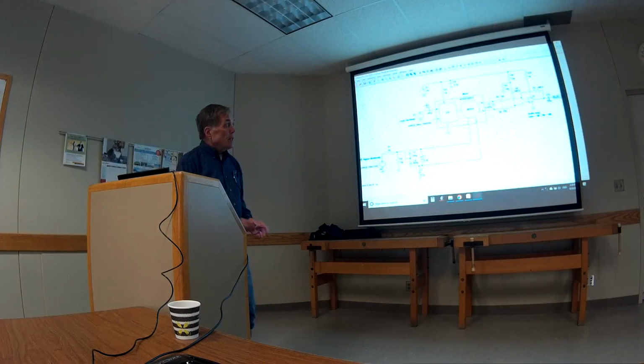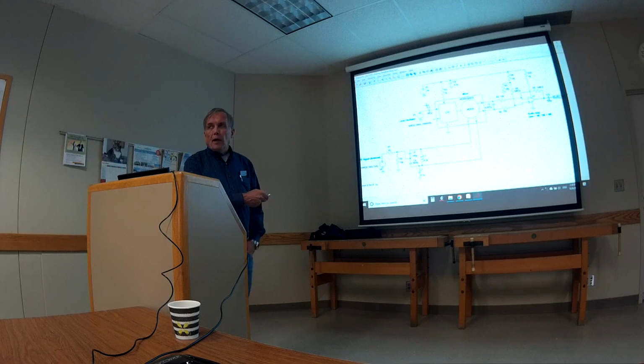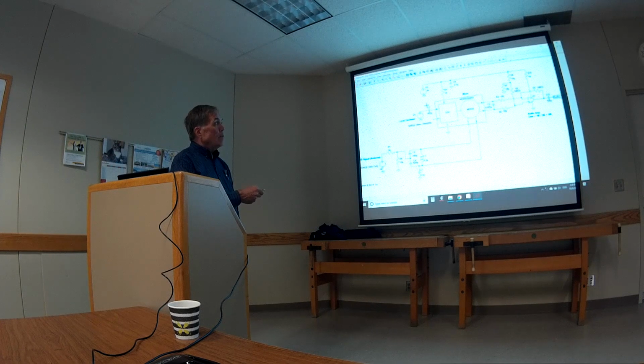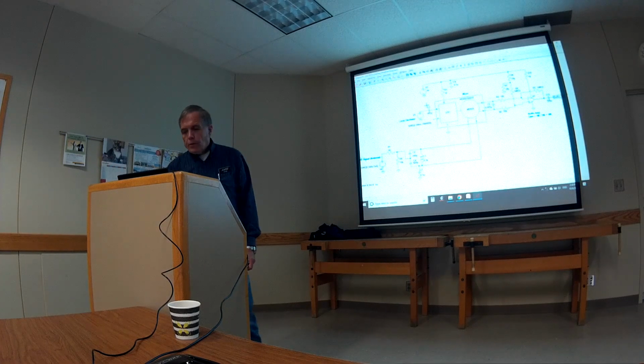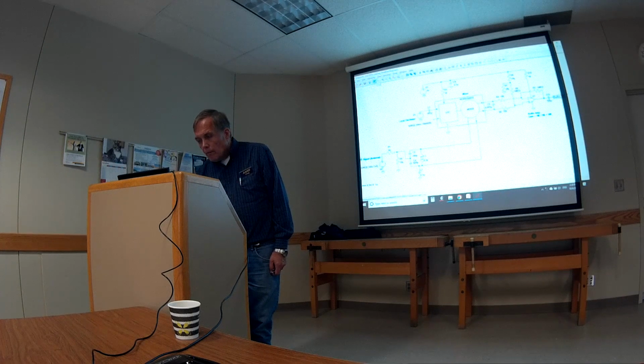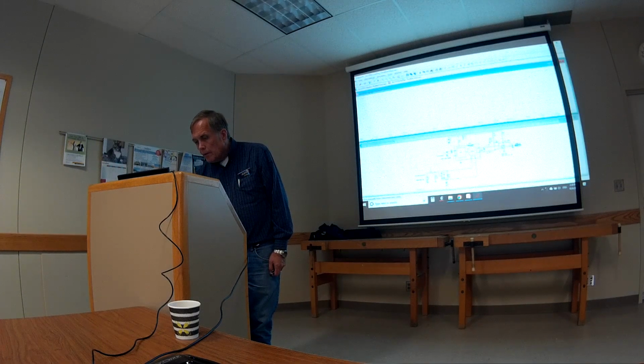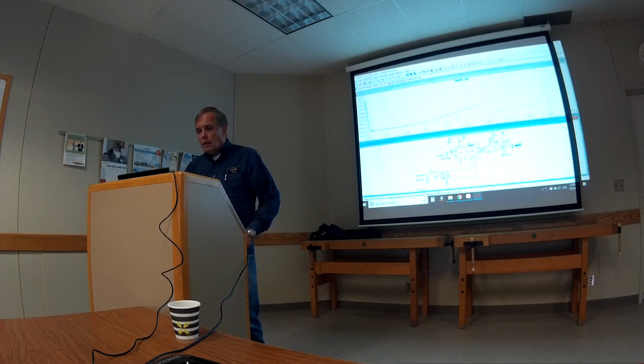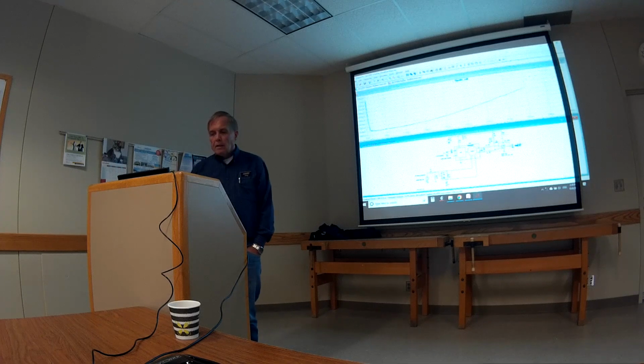So instead of an LM386 out there, I just took a common op-amp off the shelf, and I just biased it the way it commonly is. Ran in a voltage to it. And I made it with this one with a gain of 100. It took 1 meg over 10K, and that's 100. So it's going to multiply it with a gain of 100. And now this one will run. Let's wait just a second.